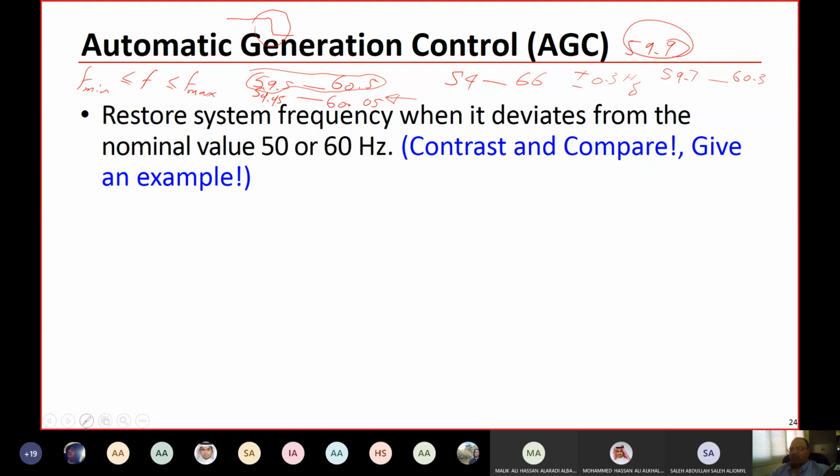If we have 5% disconnection of load, would it be possible to remove this deviation of the frequency, or do we need to increase the percentage to 10%? These are scenarios that should be set by the power system engineers. Each utility has its own policy here. Is it clear? Yes, it's clear.